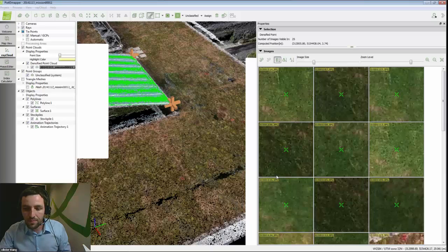Areas I desire to map do not have cell service. Is this a problem for mapping? No, it's not. We don't need a cell phone connection. We don't need data connection to do the 3D mapping and to use Pix4D Mapper. What we are going to introduce very soon is the possibility to pre-cache the images. So when you have data connection, you can pre-cache an area to have the map data saved without data connection, and then when you're flying, you have the background map that still shows nicely.